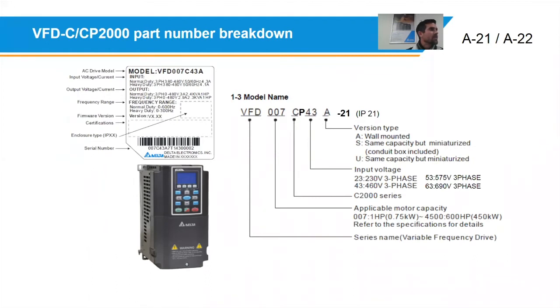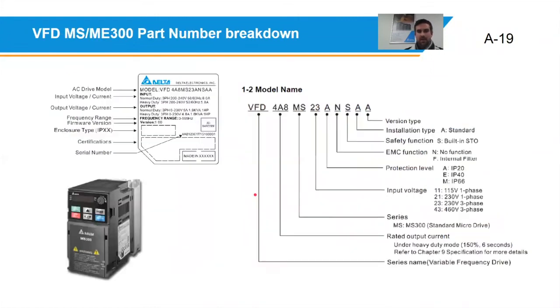Are the motors connected in star or delta on a VFD? Well, that depends on the motor. Typically, let's go back a few slides if you don't mind. If your drive is typically a 220 volt single phase drive, then your smaller motors will be connected in delta, 220 volt three phase delta. So it's important that if your drive has a 220 volt rating, that means the output voltage is also 220 volt. So look on the nameplate of the motor.